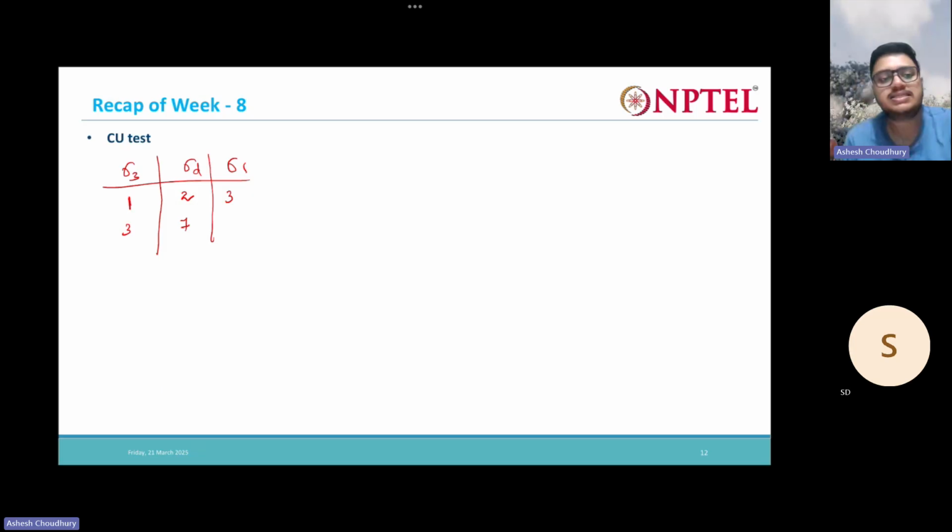As soon as you increase sigma 3 from 1 to 3 and allow the sample to consolidate, the soil will consolidate more. There will be a volume change in the sample, so obviously it will be able to take more load. Now it will take a load of 7, so my sigma 1 has become 10.